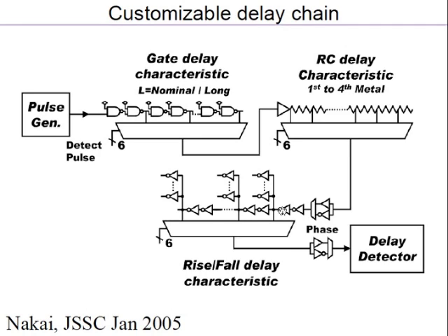In silicon, they'll instantiate this piece of circuitry which they can configure to get the model. Now this model which they configure is done once per design. If they have an MPEG decoder, they take the same IP, they put it in, but then they say, okay, this is the setting for the mux. They don't change it chip to chip. That becomes too intense a process, if for every chip you go and figure out the setting. But an MPEG chip will have, a processor chip will have a different setting and so on. So for a class of chips, you do the design once, you instantiate it, but you just configure the setting differently for different classes of chips.